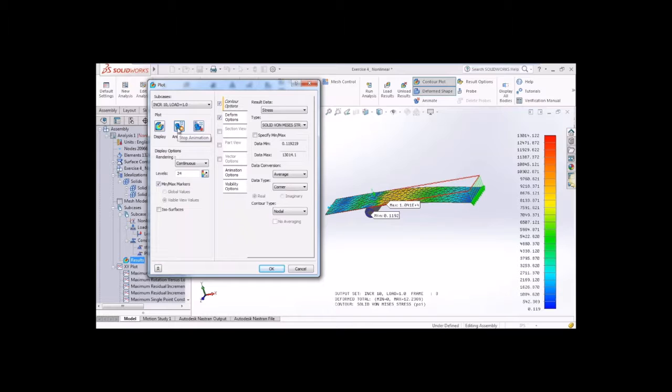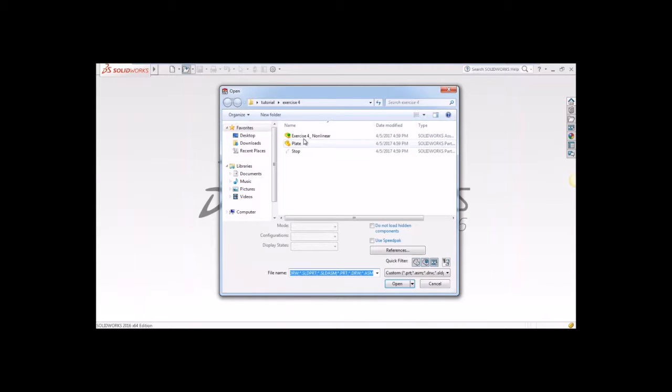While talking about large deflections, we are referring to translations or rotations of the part. For an instance, if you expect a part to rotate or deflect by 45 degrees, then a non-linear analysis would be required. And also, non-linearity has to be used if contacts and follower forces are present. Let's now jump right into the tutorials.